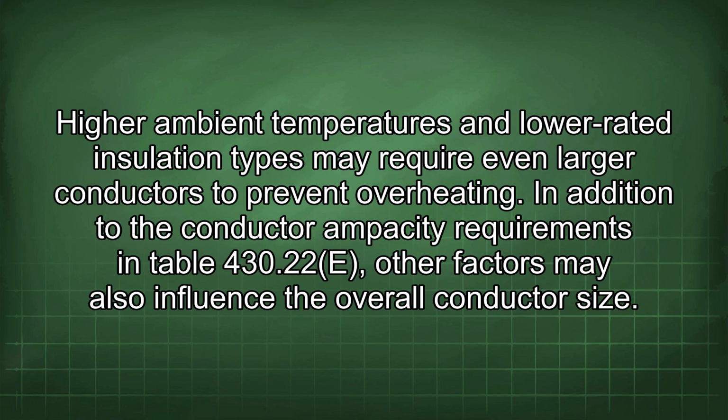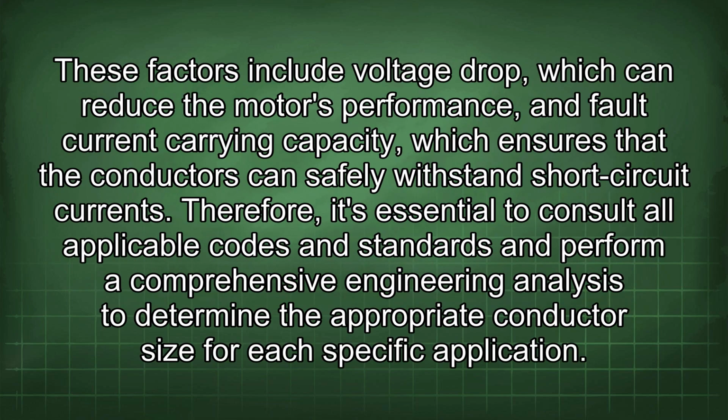In addition to the conductor ampacity requirements in Table 430.22(E), other factors may also influence the overall conductor size. These factors include voltage drop, which can reduce the motor's performance, and fault current carrying capacity, which ensures that the conductors can safely withstand short-circuit currents. Therefore, it's essential to consult all applicable codes and standards and perform a comprehensive engineering analysis to determine the appropriate conductor size for each specific application.